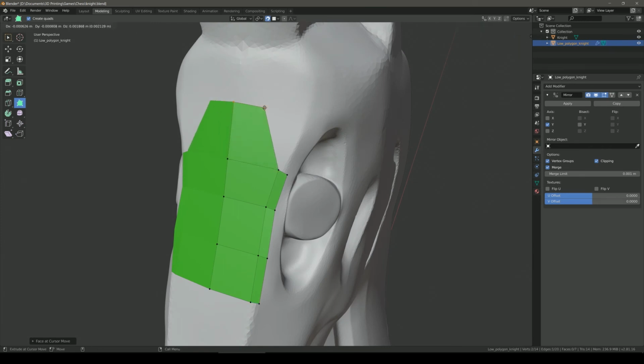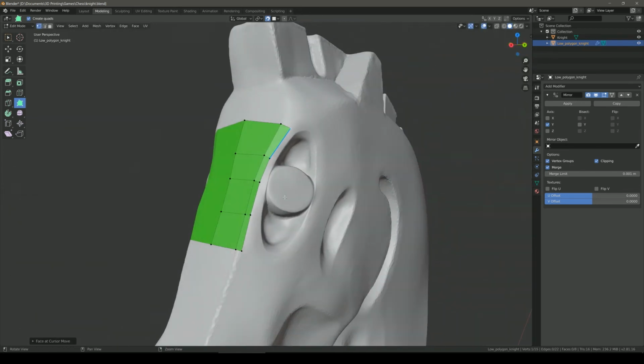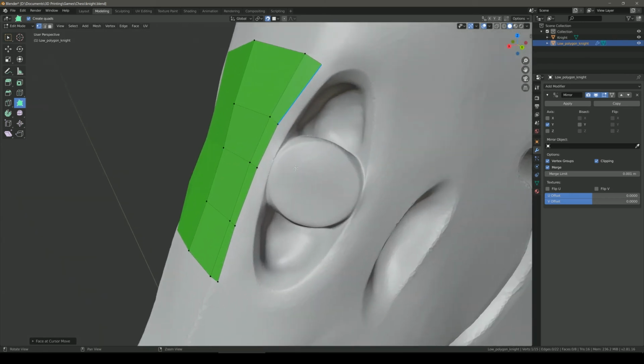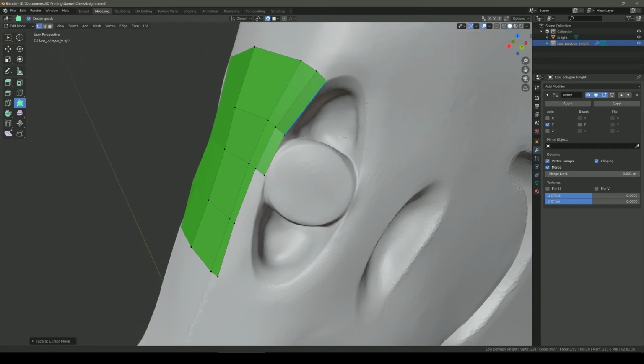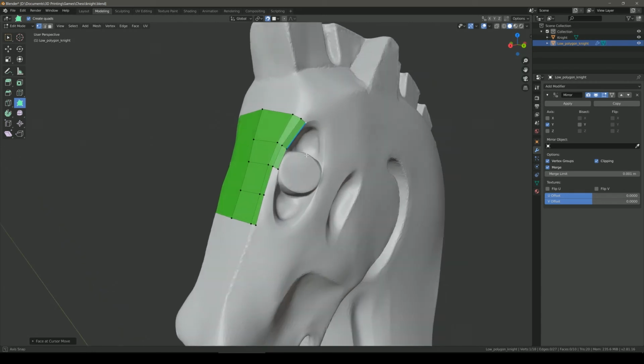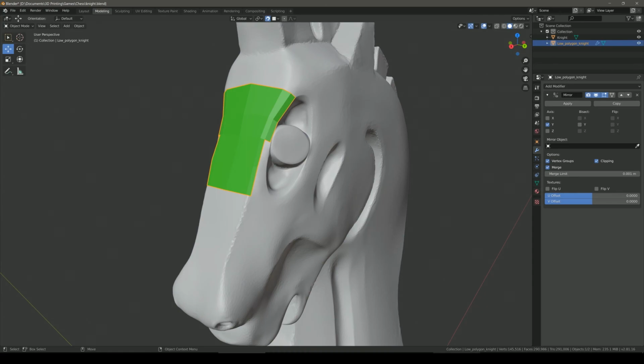So this is a fantastic workflow for making a low polygon version of a model. You would trace the whole thing as best you can. Then you would UV map the low polygon version, and then bake the normals of the high polygon one to get the normal map. Let's just finally take a look at texturing in Substance Painter.